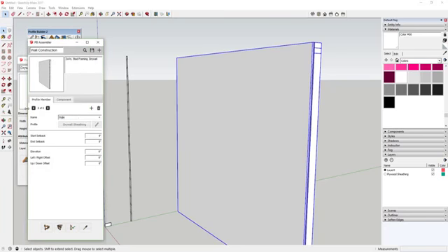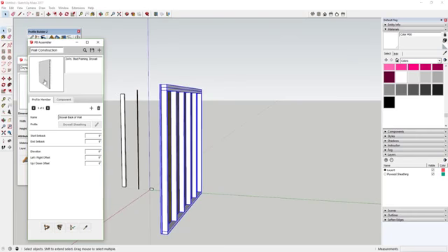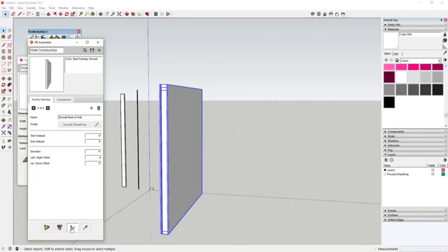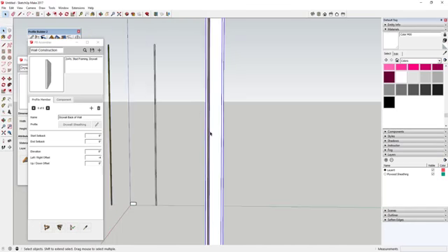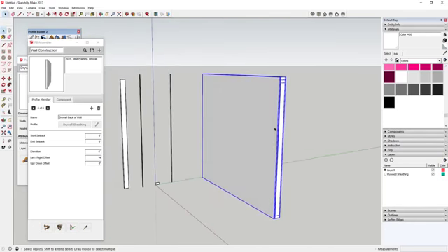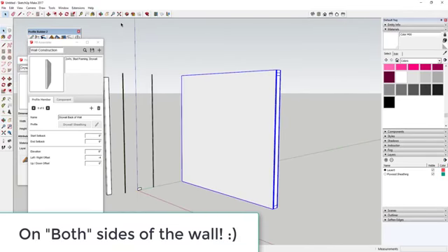We're going to call this drywall back of wall, just like this. And then remember, what we're going to have to do on this one is set our left-right offset to -4 because we want it to show up on the other side of our wall. So you can go ahead and apply that, and you can see what that did is that offset this to the outside of this wall just like this. So now you've got this wall assembly that's got stud framing, plywood sheathing, and drywall sheathing on one side of the wall.